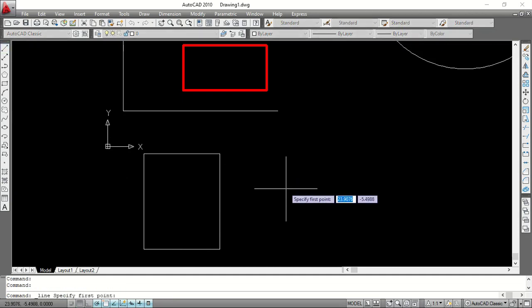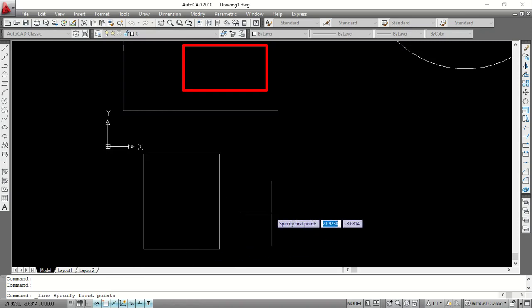Now if I click a line, there is a blue highlighted text asking me to put the dimension, or the starting point of the line. This can be very useful throughout your design with AutoCAD, and there is a particular command that controls what you're seeing there, which is dynamic input. If I turn that off, I don't even know what is happening, except I come to the command line. Only the command line here. You check below here, the command line, you see, specify first point. Most times, you may not have the time to come and look down, so you activate this so you can see the same thing. It's easy working while seeing it move around with you.